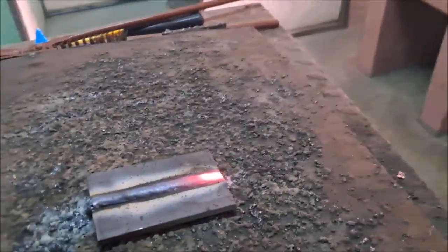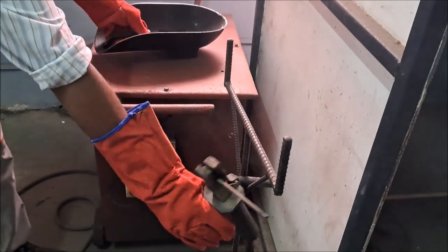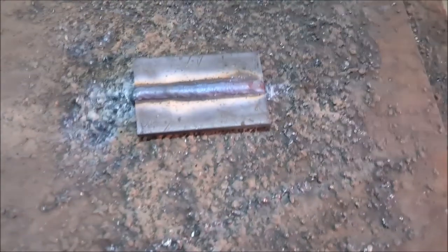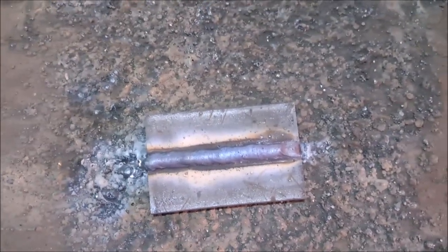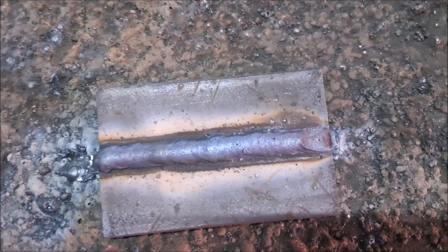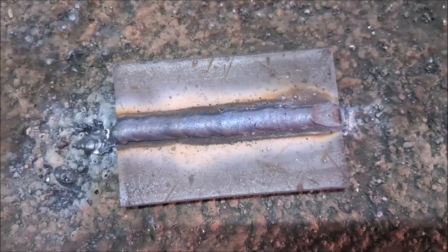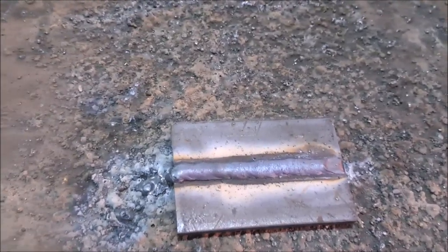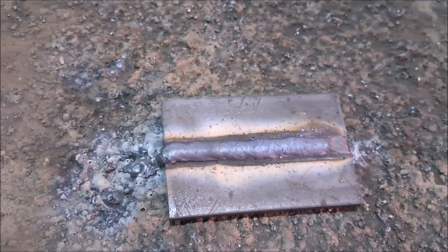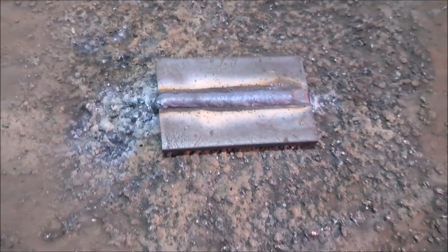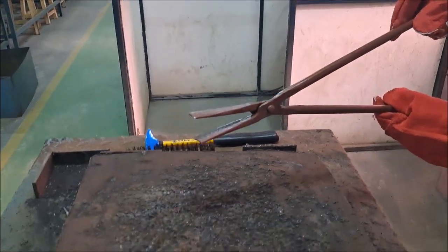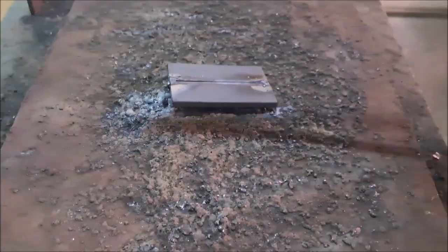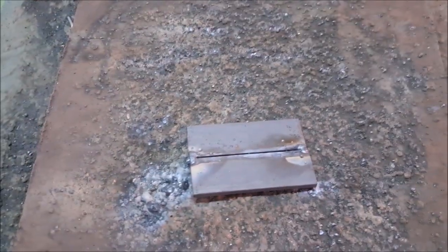After completing welding, hold the holder in the stand, then see that this is the butt joint. See that the metal has fully penetrated like this way. How to maintain this welding: when you do the welding, continuously feed like this way, then only is full penetration possible, otherwise there is no full penetration in your material. Then change to the other side, using the tongs to flip it. The same procedure: take the holder.